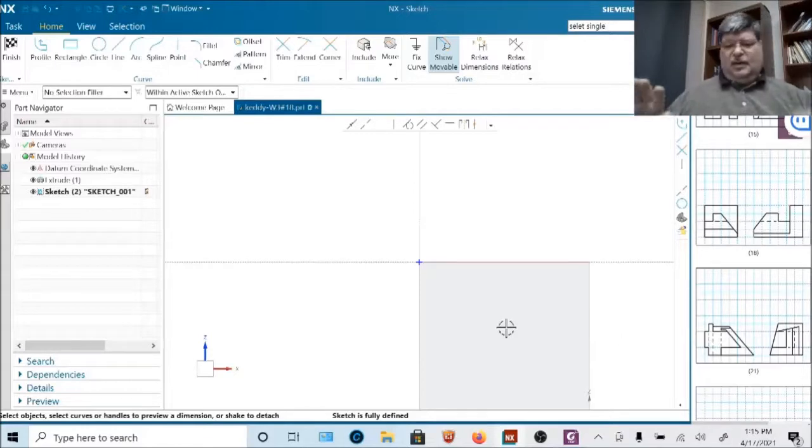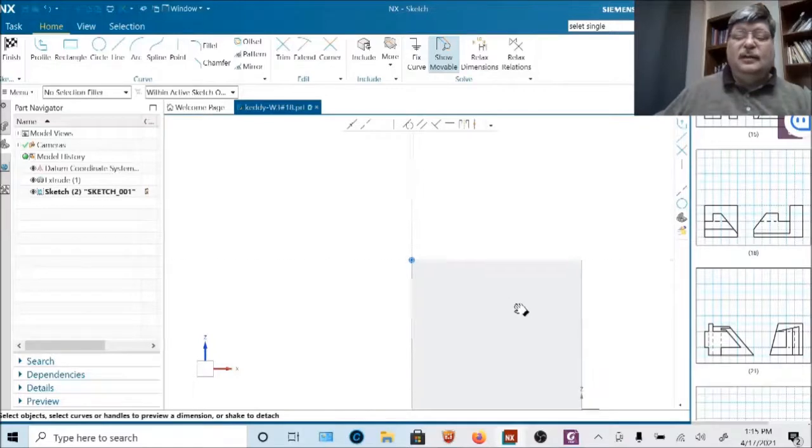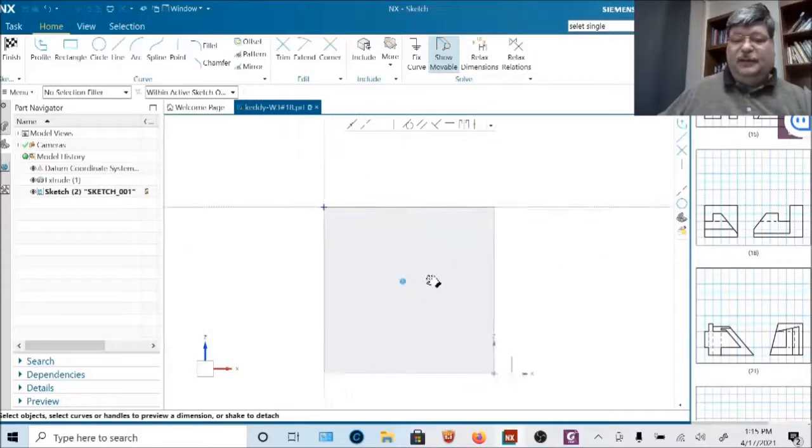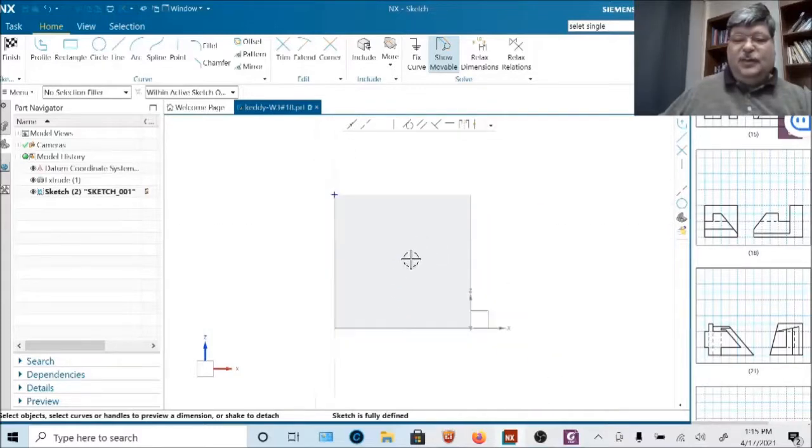And as we're a little bit off center, so I'm going to pan it, click and drag the mouse button 2 and 3, center mouse and right mouse button, click and hold those and you can pan. Okay, that's panning. Zooming is the roller ball, and it always zooms about where the cursor is, so put the cursor where you want to zoom in and out to.